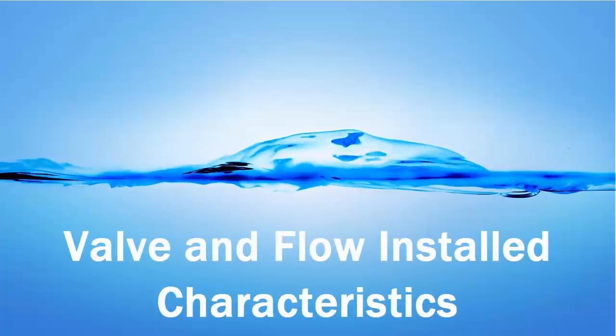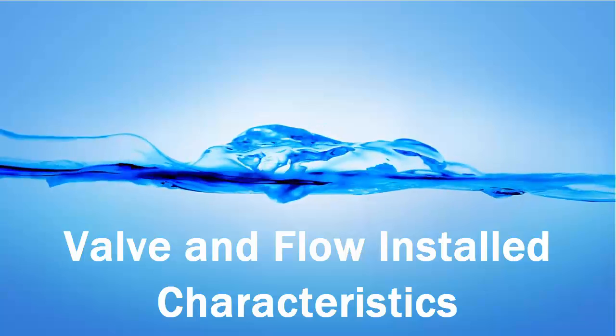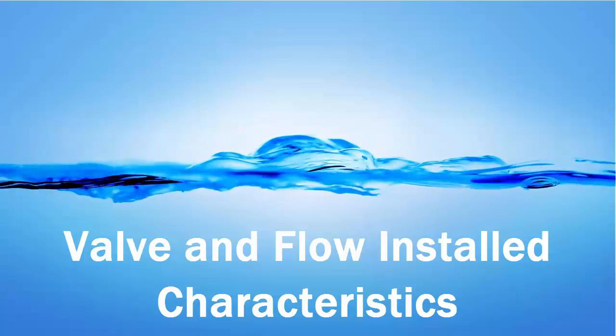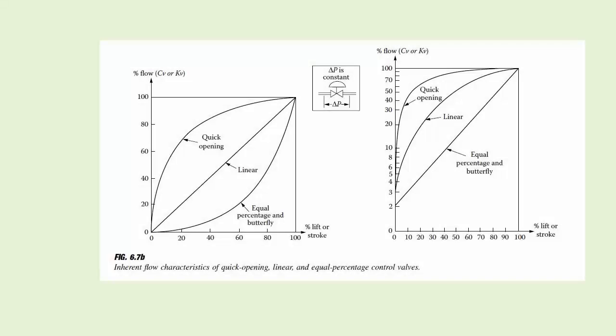Topic is about valves and the impact of the control valve characteristics on installed flow measurement. This is a plot of a typical response curve of the valve CV versus valve lift for various types of valves in industry: linear, equal percentage, and quick opening. These valve characteristics are obtained with a constant dP over the control valve. So these are ideal world conditions.